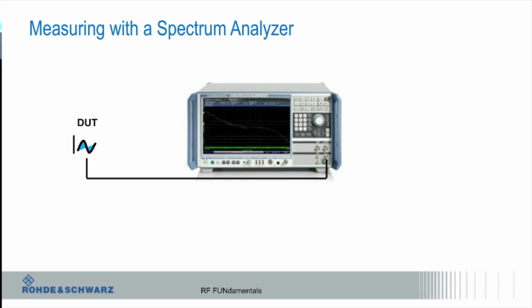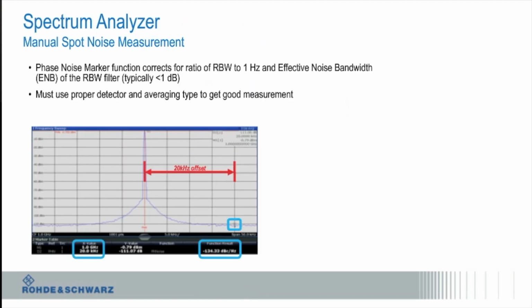If you put it in phase noise mode, it's going to show you that curve, right? And depending on how you set it up, do I want the phase noise at given offsets? Do I want the integrated phase noise? Do I want the jitter or whatever? It'll tell you all that. It's simply put that in, connect it, and then put it in phase noise measure mode. And what do you see?